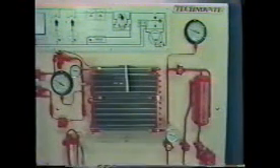Near the inlet, there's mostly liquid. As the refrigerant travels through the coil, it picks up heat from the air passing over the outside of the coil. As it absorbs heat, more and more of the refrigerant vaporizes. By the time it reaches the coil outlet, the refrigerant has evaporated and is slightly superheated. This kind of direct expansion evaporator may also be called a dry expansion evaporator because the refrigerant is no longer in its liquid state at the evaporator outlet.